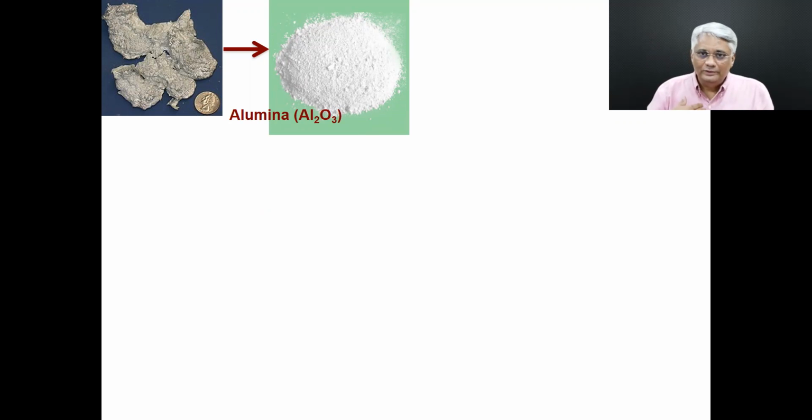And with phosphorus doping, you're getting a donor level very close to the conduction band. The donor level sits a few milli electron volts below the conduction band. So even at room temperature or a little above, it's easy for these carriers to be pumped into the conduction band and conduction happens.